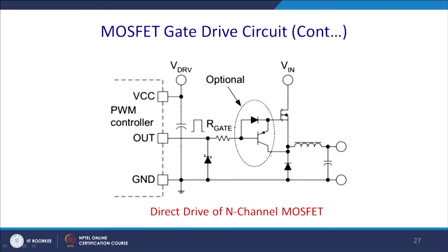You can see that if you have pulses and this N channel MOSFET, with this kind of configuration after RG you can get faster conduction. While turning on, the path will be through one route, and while turning off it can go through this one. So, you can ensure a faster turn off operation by putting in this optional component, because turn off, as mentioned in the data sheet in the class earlier, is the biggest challenge.